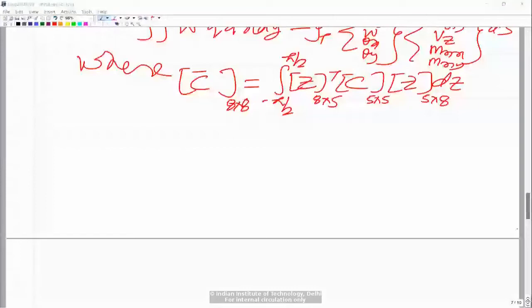So these should be degrees of freedom at the nodes of the element, particularly the boundary nodes of the element. So there would be 5 degrees of freedom at each node. And suppose we go for a 4 noded quadrilateral isoparametric element, then per element there would be 20 degrees of freedom, 5 degrees of freedom per node, and 20 degrees of freedom per element. That is the kind of interpolation we would use for this element.